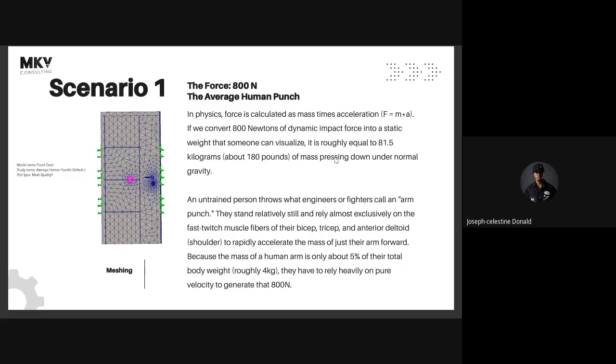So using that, we can easily mesh. And when you look at this mesh, you can see that the meshing converges at certain points. This was done using mesh control on spaces where you want it, where there are features like a fillet or a chamfer that are so tiny.